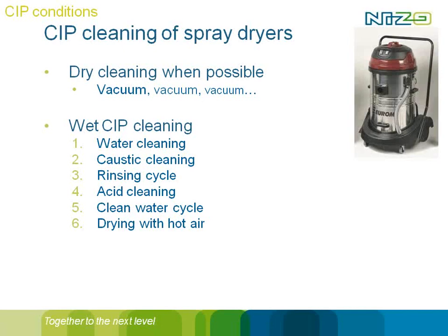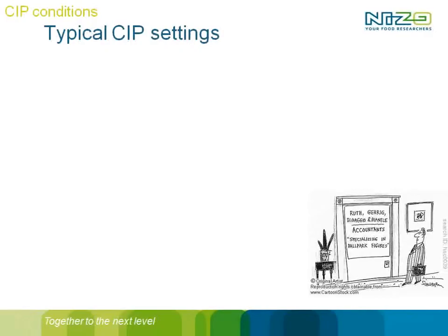water remainings in your production process, because the combination of dry powder with water will always result in extra contamination, extra growth of bacteria, because powder does contain bacteria that can start growing as soon as water is available. So it's very important, looking at salmonella, looking at spores, to get rid of this water in order to get control over your possible risk of outgrowth in powder. So if you can prevent the wet cleaning, do. If not, in that case, dry at the end of the procedure.